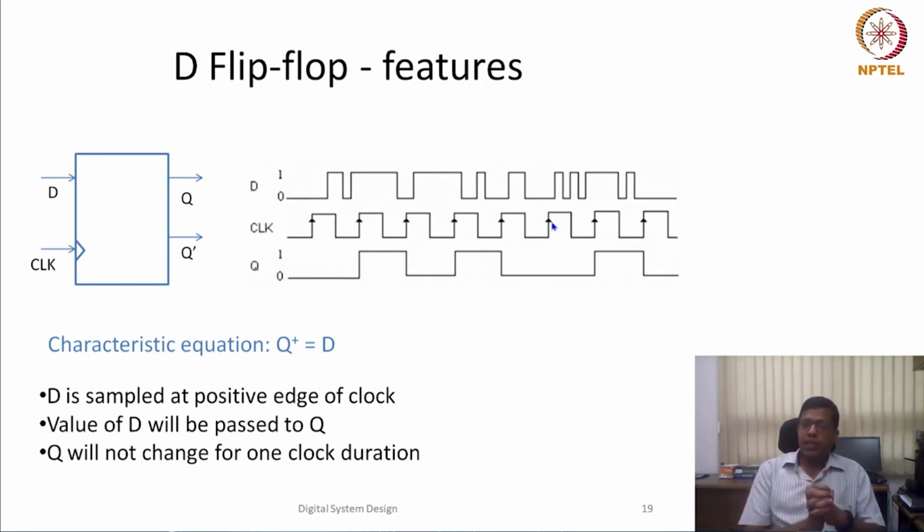We implement a 32-bit adder, and we implement it using a ripple carry adder. Let us say the input which is coming to my ripple carry adder is coming from a flip flop, which will make sure that the input to my adder will not change during that whole one clock period. Now, what should be the size of the clock period? This gives me an advantage, because my input will not change for one clock period.